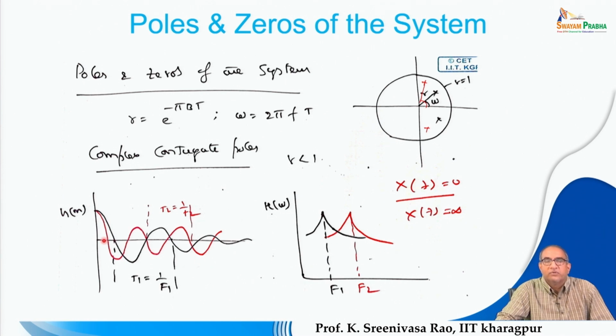So this way, once we know the poles, or you can say the roots of a denominator polynomial, you are able to estimate what the frequency response looks like. You can see the frequencies offered by those poles. In the time domain it looks like this, and in the frequency domain, each pair of complex conjugates will offer you one formant frequency. If the poles are available as complex conjugates, then you will get a proper formant frequency that you can observe.